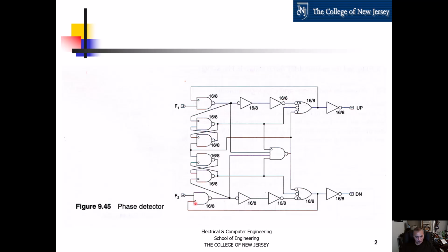So the bubble here means that input is specifically connected to the N channel transistor that is closest to ground. That is specific to that input. And that's what the bubble means for all these different gates. So again, it's a very straightforward logic diagram to implement once you implement the gates and the inverters and take into account what these numbers mean.